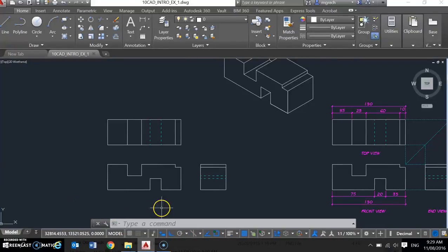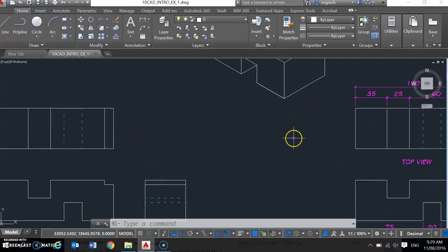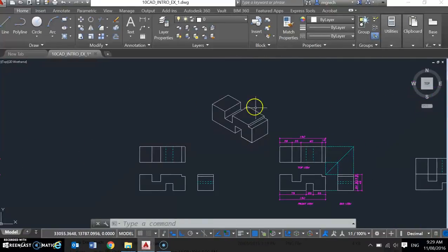You'll remember last time we constructed an orthogonal drawing of a block shape, and I've just quickly drawn that block shape in 3D because I realised it might have been a bit hard to understand what it looked like. So that is the shape of this drawing. It's an isometric drawing there, orthogonal there. So that's what it would look like. You can see this is our front face, front view. Our top view is here, and our end view is from this direction here.